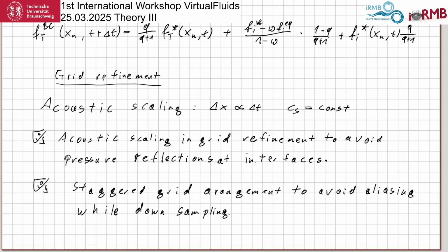But I find it a little bit, okay, I mean, you're repairing something that you know would go wrong. So if you use staggered grids, then automatically you always have to interpolate, and the interpolation is a kind of low-pass filter, and you never run into this problem, and you can do this also for turbulent flow.